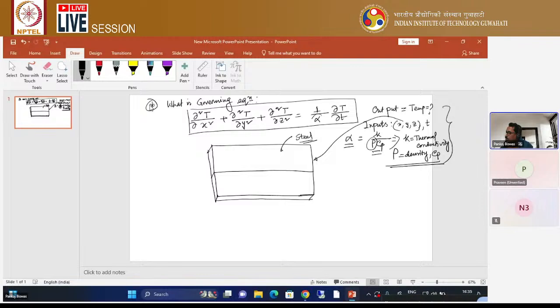So that's why this density effect will also be different on the temperature output. Whatever temperature is there in the output, its effect will be different. I have seen in most cases that researchers doing thermal analysis of the welding process, or any analysis of the welding process, generally try to avoid putting in the density. But you can imagine that density also has an effect. This is one thing.